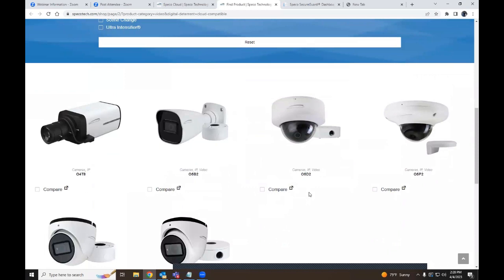So when you install the cloud cameras for the first time, they are looking for our cloud server for the first 2 hours that they're plugged into the network. Okay. This is important because it's stuff that's missed a lot. If they're installed more than 2 hours and I go to scan that QR code and attach them, I'm going to get an error. It's simply because the cloud cameras are looking to register to the cloud server for the first 2 hours they're plugged in, and then we put a pause on it. And the reason why, it's not congesting the network, always trying to ping a server, is because these cameras can be used on a typical network or on your recorders as well.